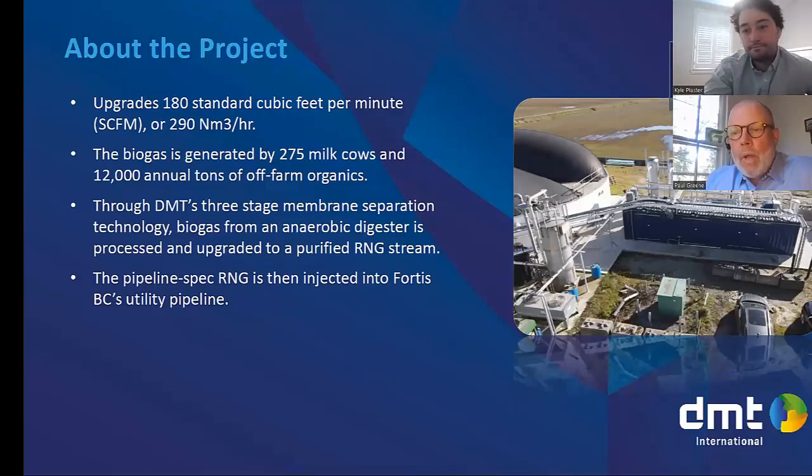So what does it take to run one of these systems? If I'm a dairy farmer, how do I operate my membrane system? It doesn't require a lot of hands-on utilization. The only thing you really have to think about is pollutants. You've got those media beds up front, and you'll need to analyze the pollutants coming out of those media beds, whether it's H2S, ammonia, or VOCs, and make sure none of that enters the membranes. So it's monitoring pollutant levels and replacing the media beds when needed, and then general maintenance, like checking filters. There isn't much hands-on maintenance, and a lot of these projects will just monitor remotely. If an alarm goes off, we'll send someone to site, but that's very rare.